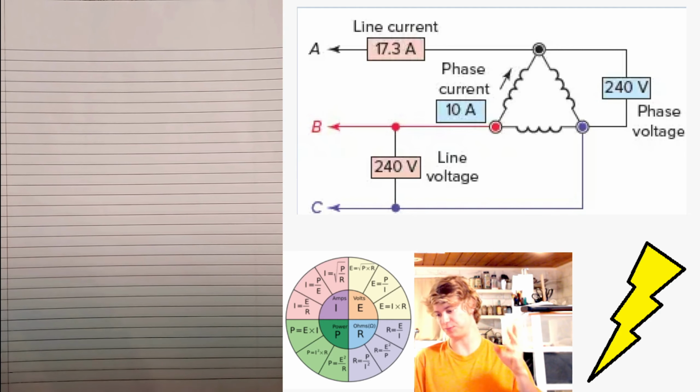4. What conditions must be met when connecting a 3-phase alternator to a power grid system? The phase sequence or rotation of the machine must be the same as that of the system. The alternator voltage must be equal to the system voltage, and the alternator voltage must be in phase with the system voltage. The alternator frequency must be equal to the system frequency.